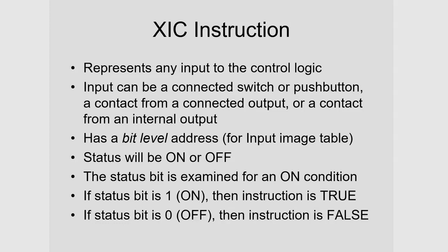We can use the examine if closed instruction to represent any input to the PLC, any input control logic. That input can be a switch or push button. It can be a contact, some kind of output contact, or a contact from an internal output. What's an internal output?